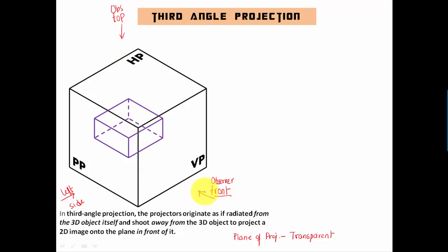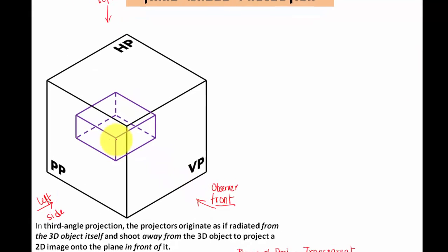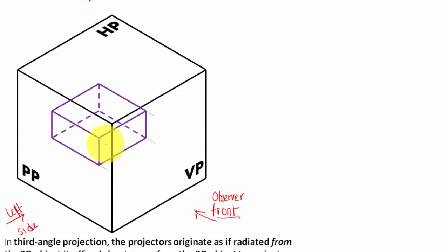Initially we're going to be looking at this object from the front, and let's draw the projector lines towards this vertical plane in the backward direction, something like this. These are the intersection points with the vertical plane, and obviously all these projector lines are going to strike this plane and make 90-degree angles. Obviously that's why this is an orthographic projection: apart from being parallel to each other, the projectors also strike the plane at a 90-degree angle. So this was all about the front view.